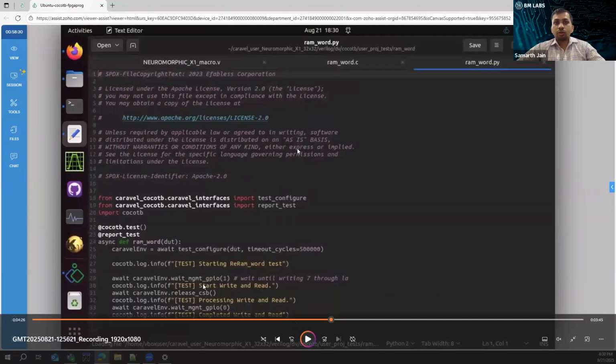the checkpoints. So over here you can see we did a write. As soon as GPIO was 1, we did the start write read, and then we waited for the process, and when the GPIO went 0, we completed the read and write operation. Yeah. So over here you can see the printed statement which we were seeing in the terminal previously,